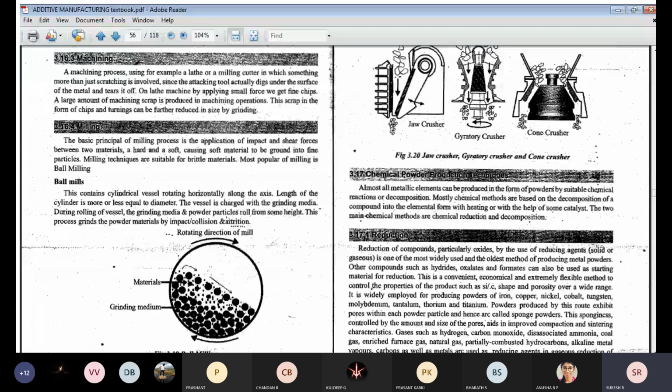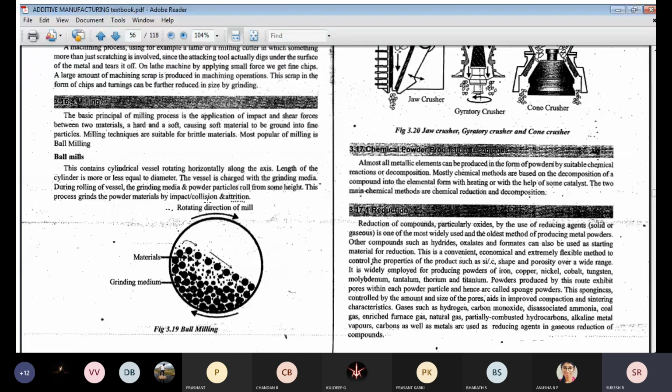It mainly consists of the motor setup. Inside the grinding medium, we're going to place a number of balls, the iron balls, especially steel balls, of different sizes. If you want to produce fine powder, we take the metal particles and pour them inside. Then we close it.